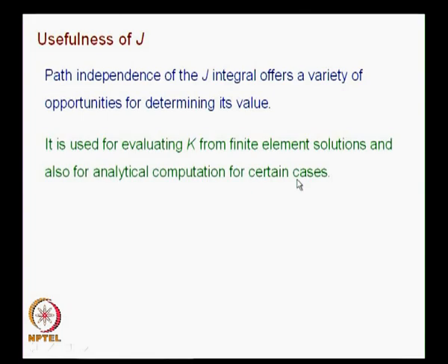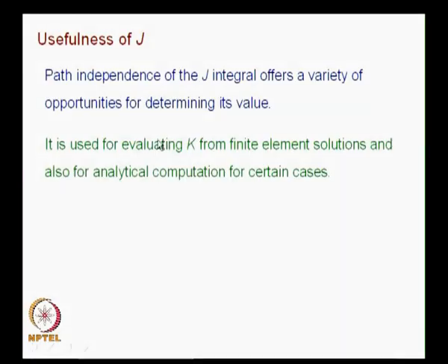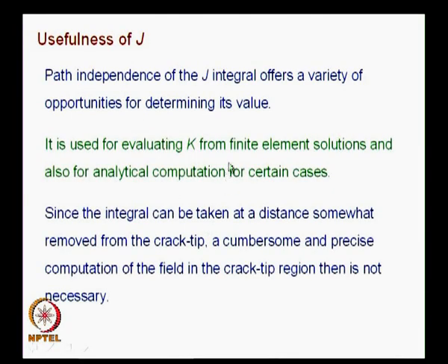And what we have done? We have first evaluated J for a known problem which you had solved in linear elasticity, and we find that the expression you finally get for J is the same as G, which is nothing but the energy release rate. And we would see further, because I have the advantage of path independence, what is the use of it in finite element calculations.